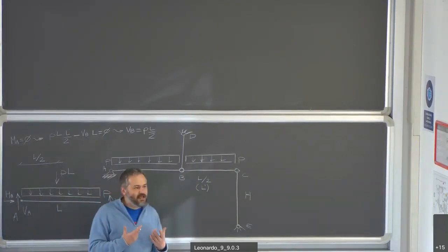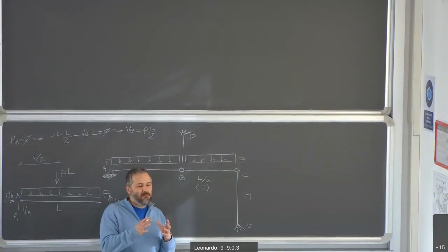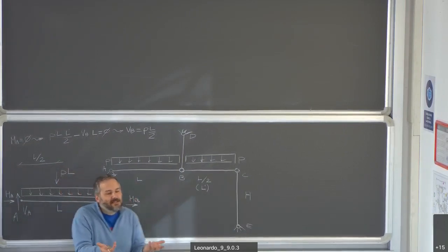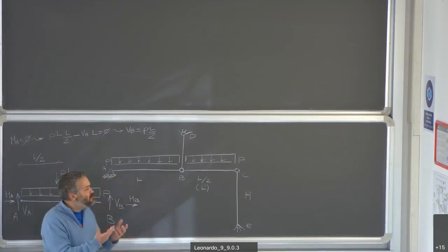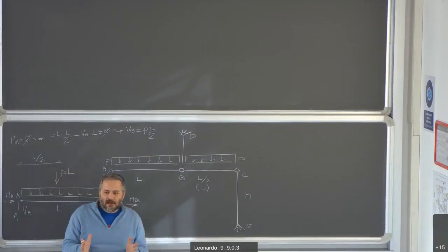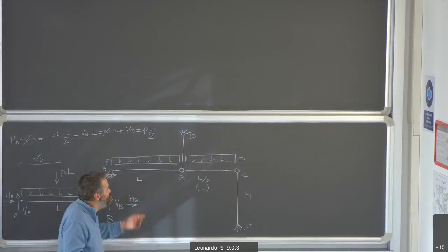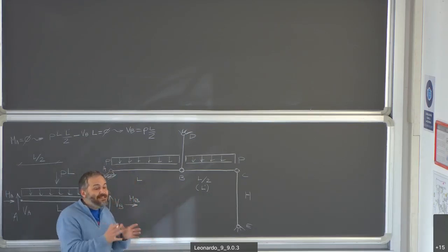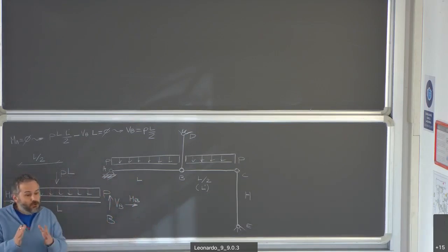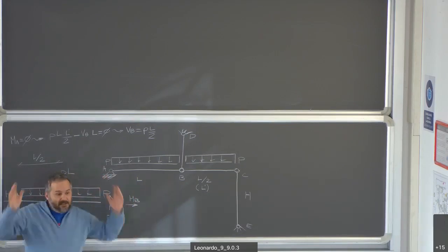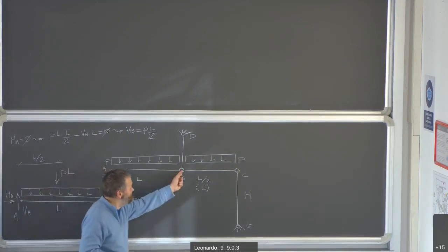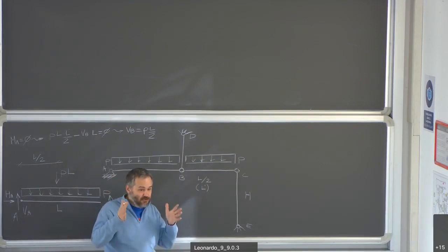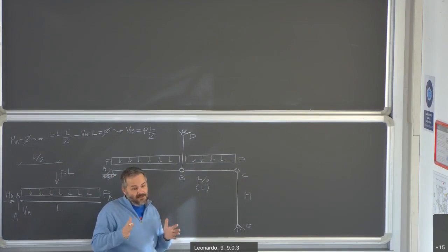But that's the problem. It's not a matter of logic. Your problem is the problem that young Patrick faced. When I first looked at this structure, it's a good point. One would look at this and without writing the equations would say, why would it be the same as a simply supported beam, since it doesn't look like a simply supported beam? And that's exactly my point. No matter what happens in the surroundings, when you have hinge and hinge, it doesn't matter what you have outside the hinges. That portion of the beam will always work as a simply supported beam.